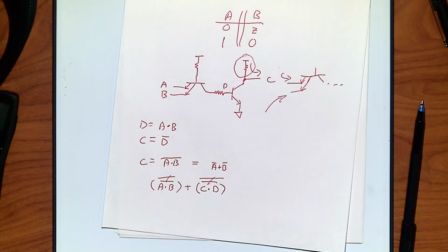So generally speaking, you're going to put an open collector output, so each device only supplies grounds, and there is a bus master, which is the only thing allowed to pull up and supply power. If there's only one thing supplying power, you cannot get a short, because that thing just protects its current limit and it's done.